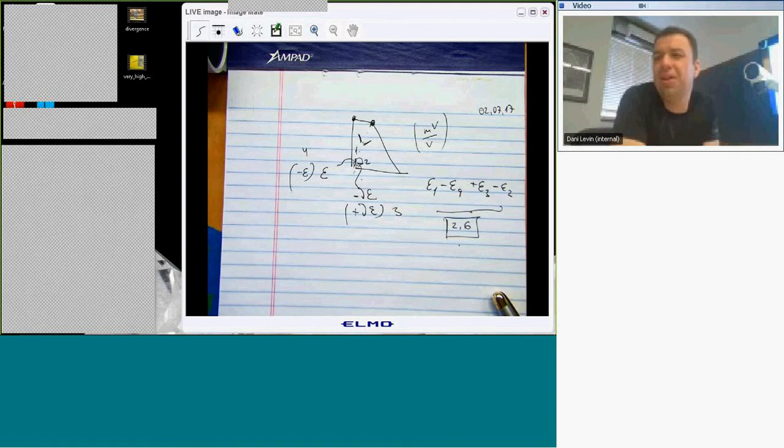But if you can, sample something like 20 times more, because what Nyquist doesn't tell you is that at twice the frequency, you won't get the actual amplitudes. You will get the frequency, but the amplitudes will be clipped. So if you can, sample 20 or 30 times more. But you might run into some instrument limitation. It's not in our case, but potentially you can.